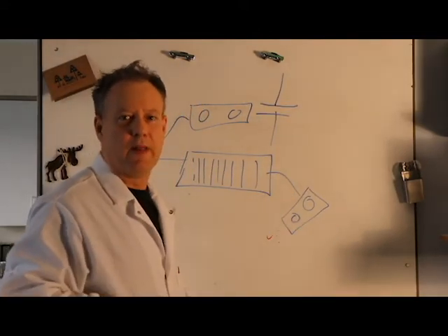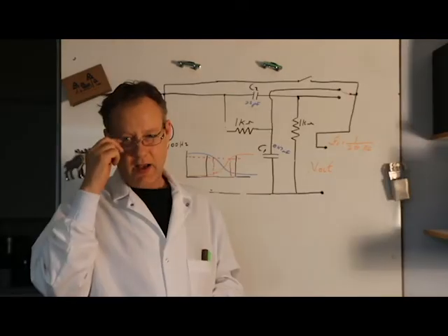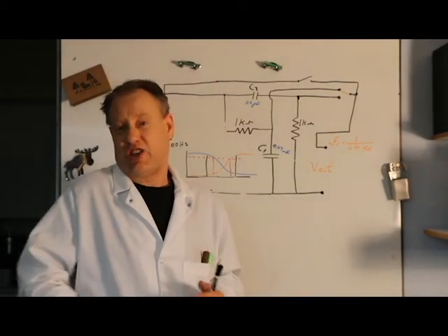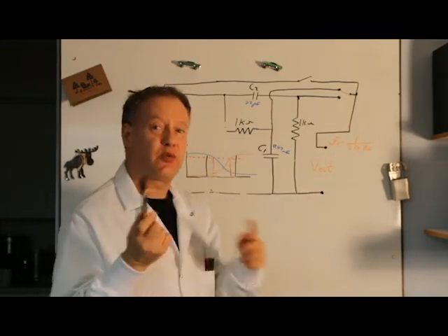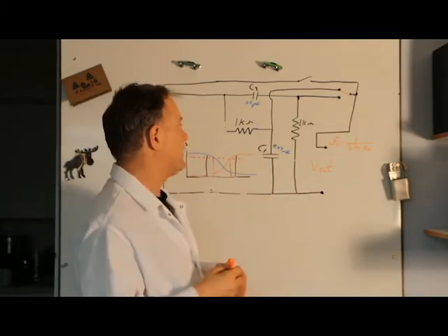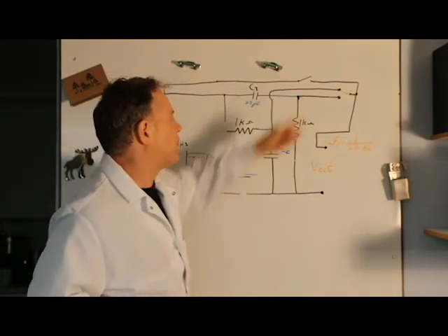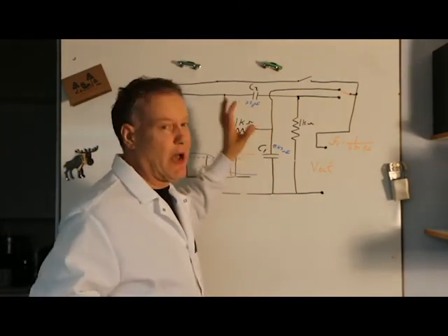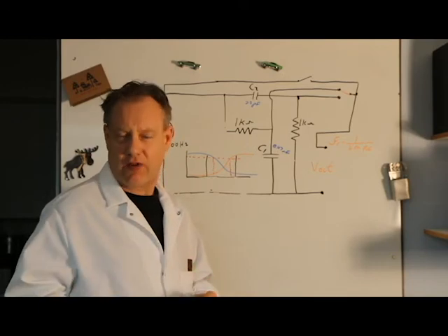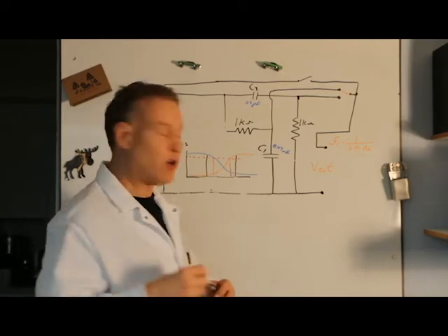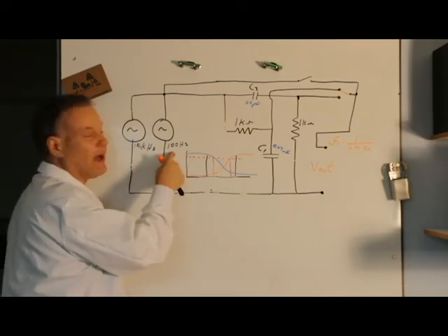Very cool things. So what I want to do now is take a look at a circuit in action. I designed this circuit, and it's got two filters in it. This switch gives me the option of switching back and forth between the two circuits. I've got a low pass over here and a high pass over here. I've also put a switch in so that I can bypass these filters completely and look at the raw waveform. The raw waveform is coming from two frequencies. This is 12 kilohertz, and that's 100 hertz.